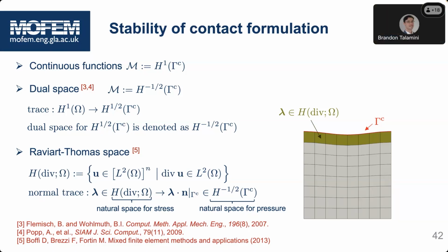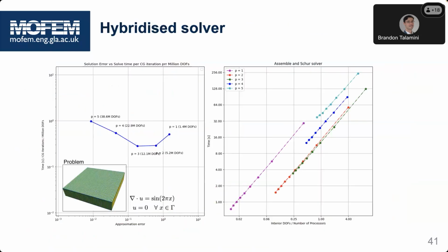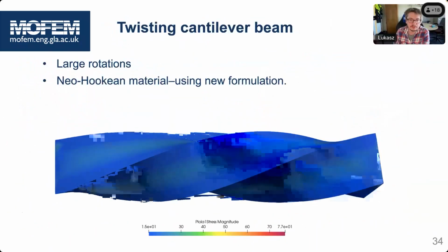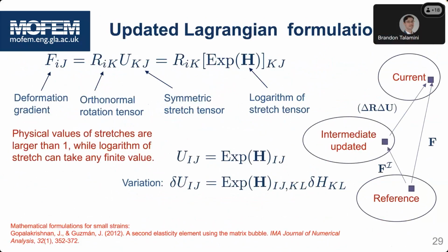Yeah, that's right. Just really quick though, that's a lot of really nonlinear fields. Do you have a sense of the inf-sup conditions on your spaces to be able to have a stable method? You showed the benchmark problem, the Cook's membrane, but do you have some sense of, like Zania was asking about the polynomial degrees you're using, what numbers are allowed, what will actually converge?